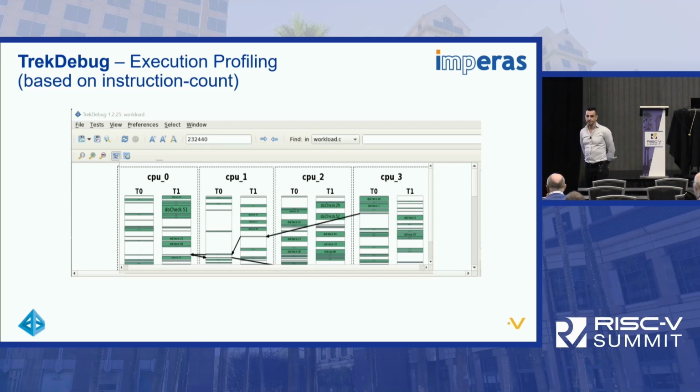This can tell you if you have a bottleneck in your design. This can give you an idea of if there's any task that you expect them to complete faster than others. So it can give you a lot of feedback of how your design is executing, not just if your test is passing, but also where time is spent or where instructions are spent.